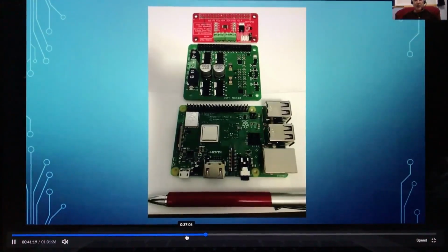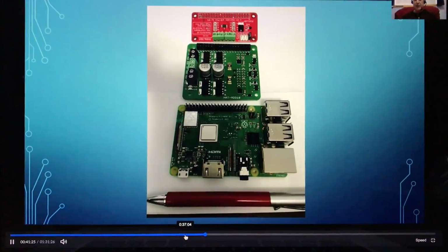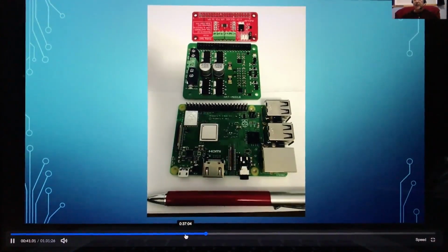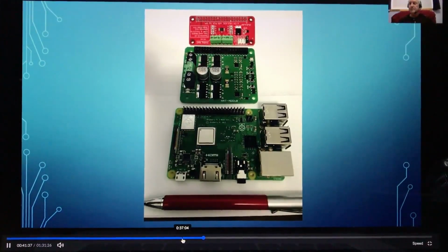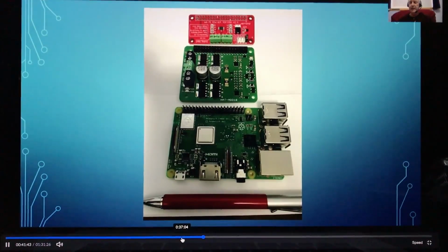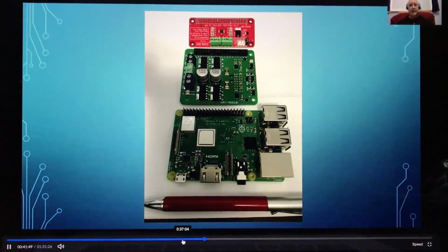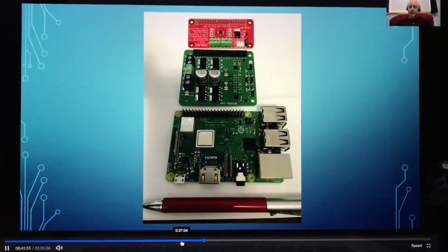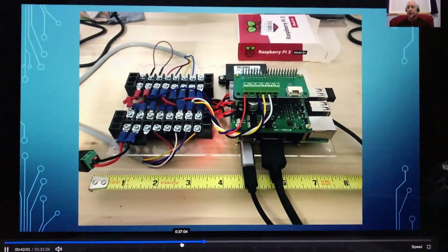Here's a picture of the main boards involved here. The bottom board is the Raspberry Pi 3B+. Next up in that list is a dual channel motor controller board used to independently control each actuator. Then next up is a 4-channel 16-bit ADC used to translate those pot position values in the actuators. And I've also got a wind speed sensor hooked up to this too. They refer to these add-on boards as HATs, or hardware attached on top.